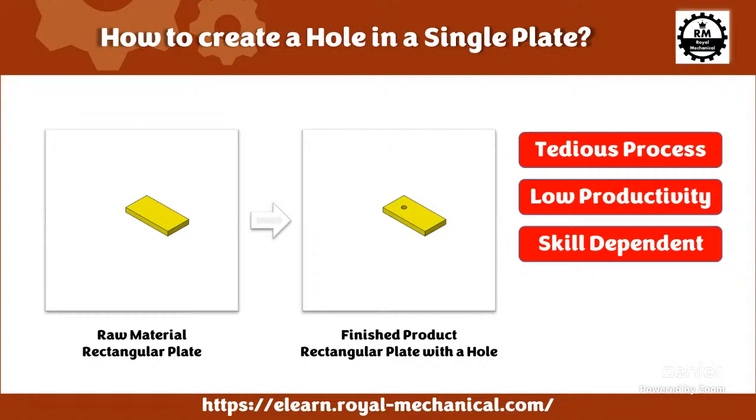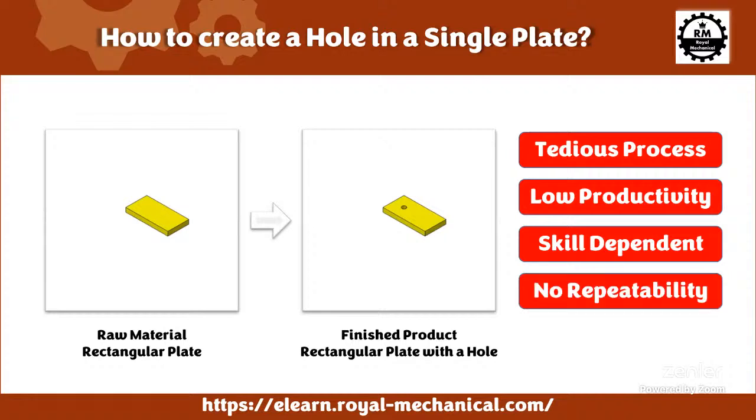it becomes low productive. And for the marking, the scribing, the punching, and the drilling, the skill of the operator comes into the picture. The accuracy and the precision of the end product will be dependent on the skill of the technician. So it will be skill dependent. And when the technician is making hundreds of such parts, there could be some amount of human error, which will creep in while marking, punching, scribing or drilling. So there will be no repeatability in the parts.